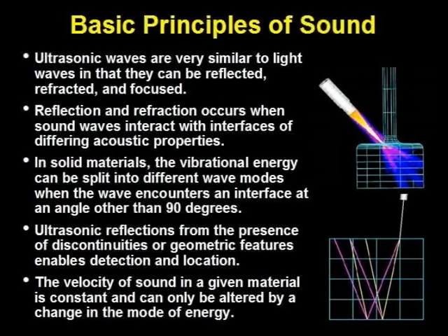Generally, the sound tends to stay in the material with higher acoustic impedance. No refraction or change in direction occurs if the incident sound is normal or perpendicular to the interface between materials. If the incident sound is not normal to the interface, the sound will refract or change direction. The change in direction can be calculated, knowing the velocity of sound in the two materials.